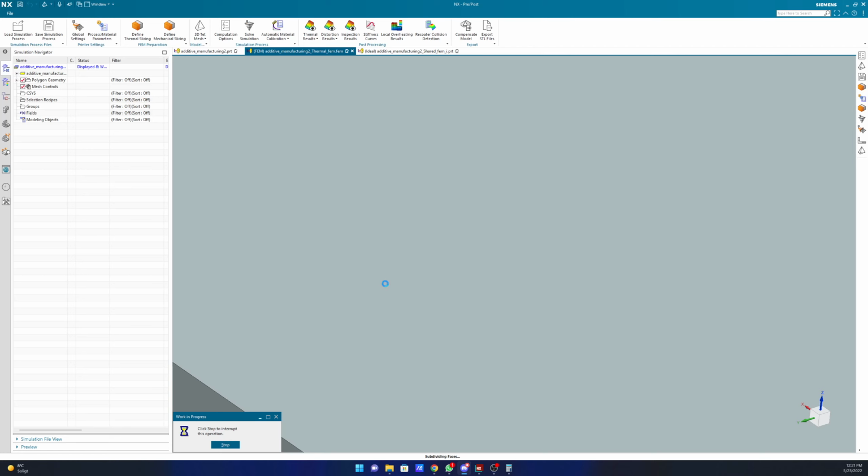On generating support in my assignment one, I realized that when I changed the block to volume for the base support, I couldn't mesh the component. It was giving me errors when I tried meshing it. But when I left all the support at block, it meshed. I don't know why. Did you simulate the supports when you created blocks?